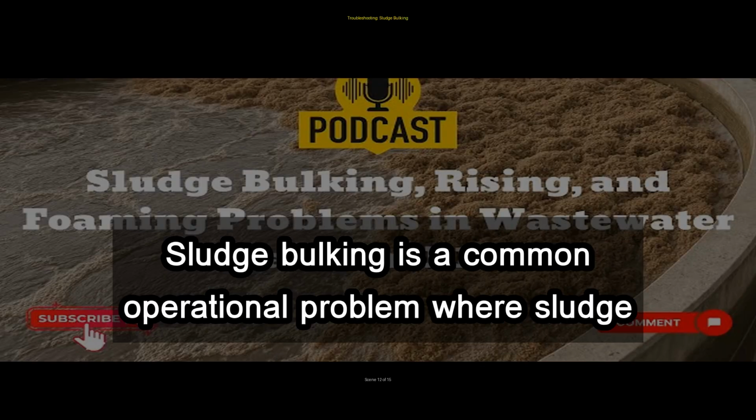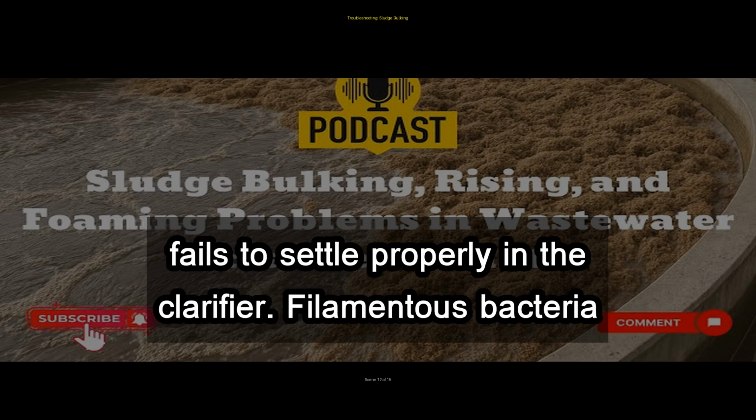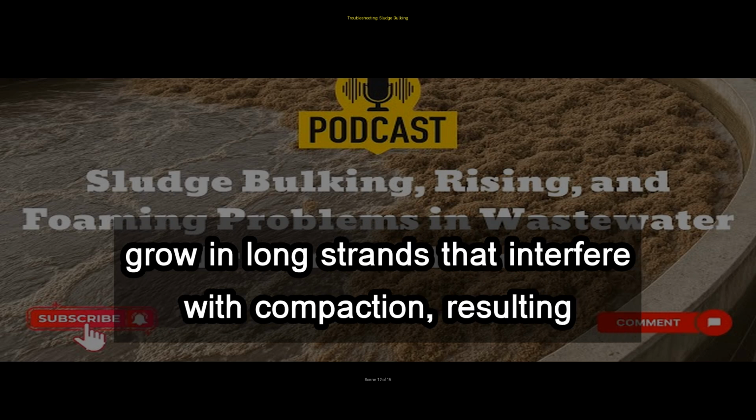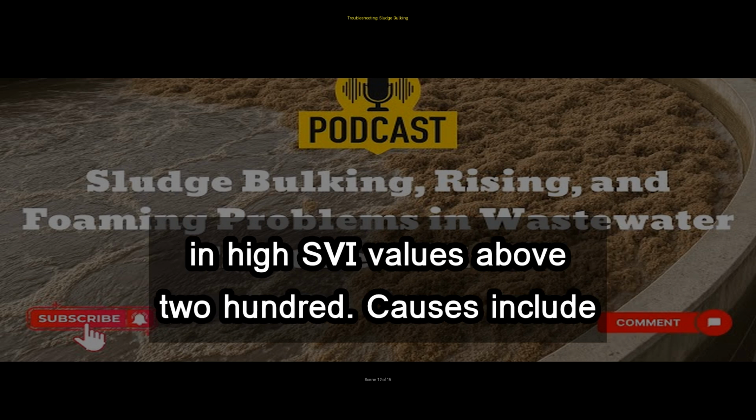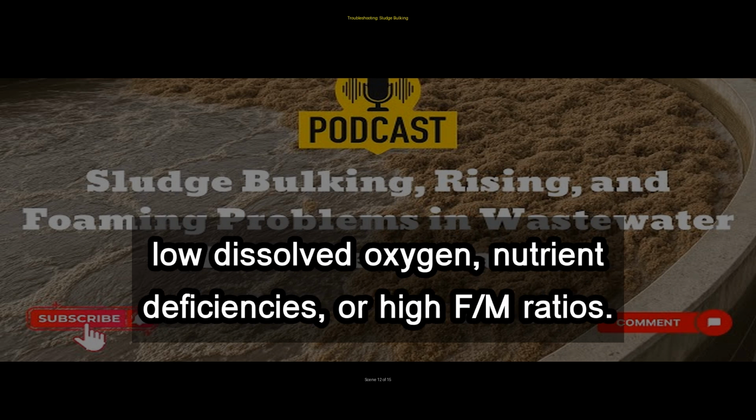Sludge bulking is a common operational problem where sludge fails to settle properly in the clarifier. Filamentous bacteria grow in long strands that interfere with compaction, resulting in high SVI values above 200. Causes include low dissolved oxygen, nutrient deficiencies, or high FM ratios.